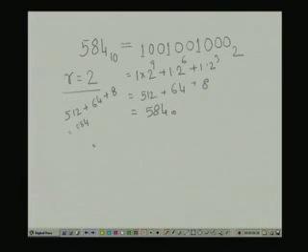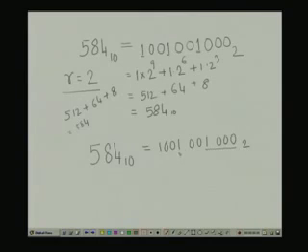So I got 584 in decimal is 1001001000 in binary. Now, I want the binary coded hexadecimal. For hexadecimal, what we discussed last day is that 4 bits we have to take together, from the LSB side. So I mark this 4, then again this 4, and 2 bits are left, so I put 2 zeros there.